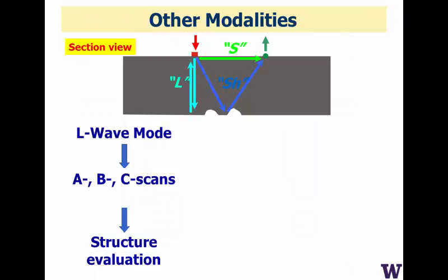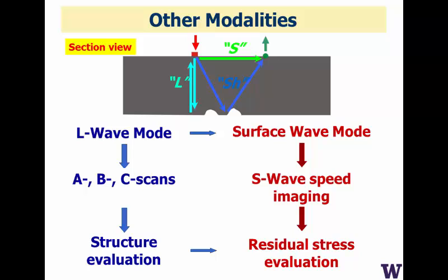Okay, let me conclude by saying that what I've shown you is mainly in composites and just longitudinal waves. The same system can be used for a lot of different applications. We can do all mode types. We can do, as I said, in the composites, mostly compressional waves, but we can do surface waves, shear waves, Lamb waves, all the different structures, just changing the shape of our excitation beam in optics.